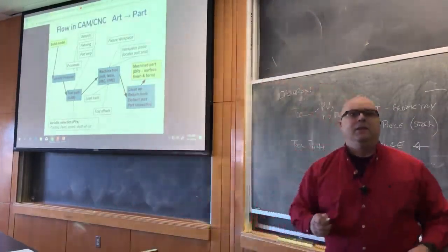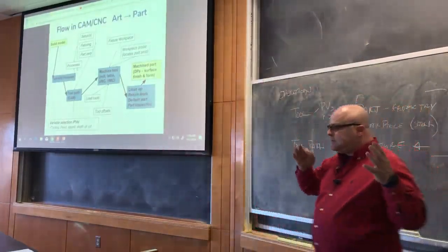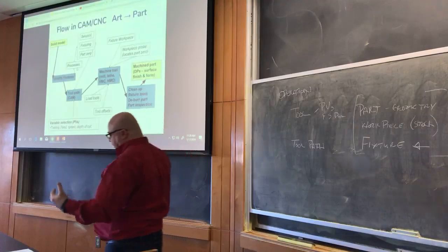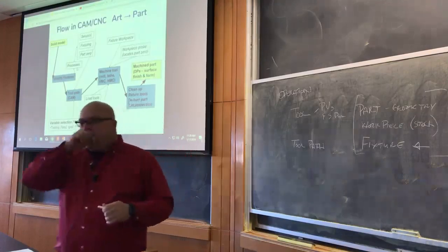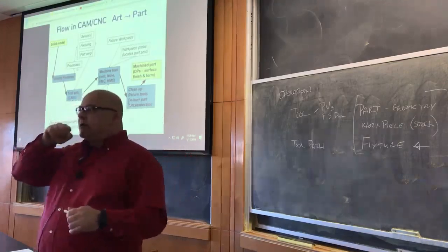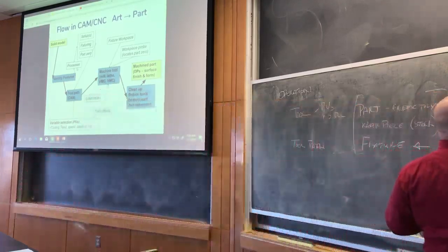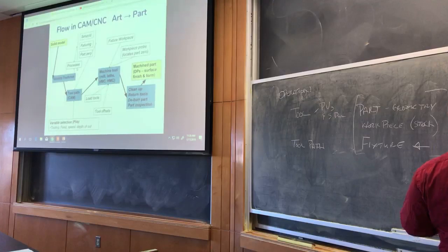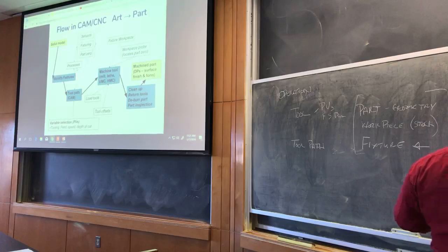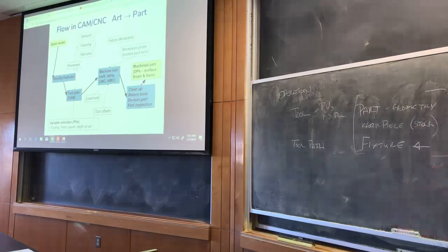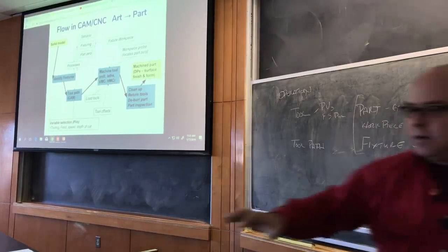Found it. Okay, so we've got to think about how the tool is going to come into the part, how it's going to come out of the part. What's the surface speed? If we look at the bottom of an end mill, it looks something like this. Maybe we'll draw a 3-flute end mill. And so we look at the bottom. If you looked at the side view, there'd be a spiral going up the side, right? We're looking straight down at the bottom of it here.